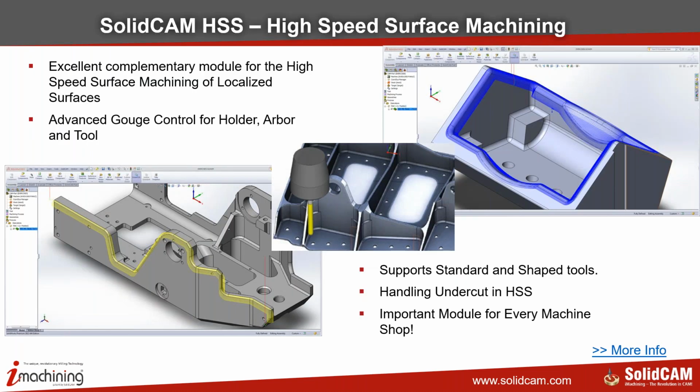Apart from the 3D machining functionality, we also have high-speed surface machining. High-speed surface machining basically is a localized surface machining technique available inside SolidCAM, where you can select only the surfaces, no need to define any kind of boundaries, and the software will try and detect the machining pattern and machine either using the flow line technique, or it could go with constant Z technique, or it could go against the flow line or 90 degrees to the flow line technique. So it can do various methods, or it can provide various patterns for machining local area surface.